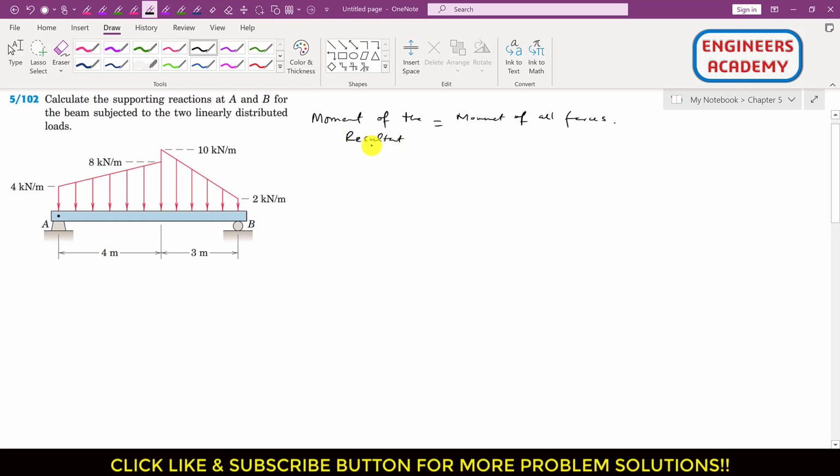If you want to find the moment of the resultant of all these distributed loads about this point A, let's say the resultant of these distributed loads is located somewhere here. Let's say this is the overall resultant of all these distributed loads, and the distance of this resultant from point A is x bar. So the moment produced by this R about point A will be x bar times R.